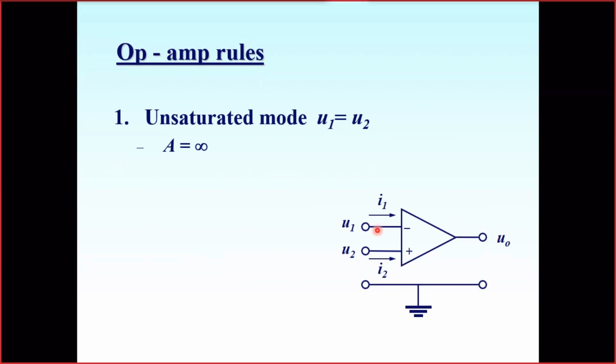In the inverting amplifier, when we have a positive voltage on the input, this voltage will appear on the output with a minus sign. So the output is growing negative through the negative feedback. It comes to the inverting input, and the voltage on the inverting input reduces the output voltage. That actually leads to the non-saturating operation of the amplifier. So the output is not saturated when we have a feedback.